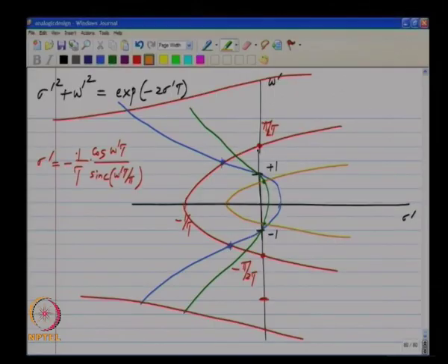We expect that the amplifier will respond only to its input, it will give you k times the input voltage after reaching steady state, but if the amplifier is unstable, it is not going to do that. Even without an input, it is going to give its own output, and the output is going to be unrelated to the input and it will soon become very large. Okay. So, the amplifier becomes unusable if the poles are in the right half plane.